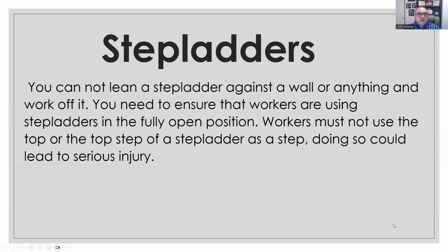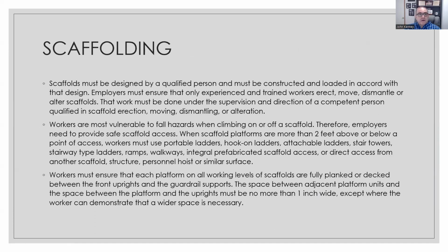Step ladders. You cannot lean a step ladder against the wall or anything to work off of. You need to ensure that workers are using step ladders in the fully open position. Workers must not use the very top of the step ladder as a step. Doing so could lead to serious injury. I've seen these ladders used so wrong on so many projects. They're not meant to be leaned up against a wall, unopened, to get to the next level. Use a step ladder correctly or you will have injury or fines.